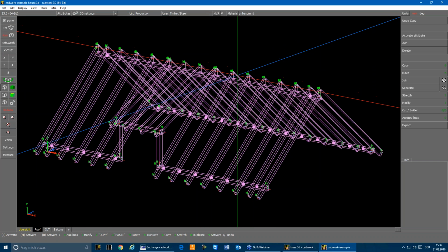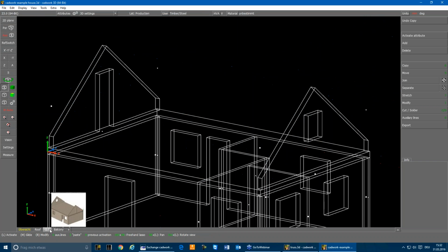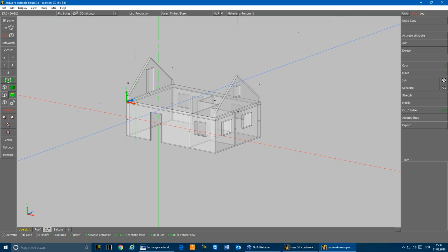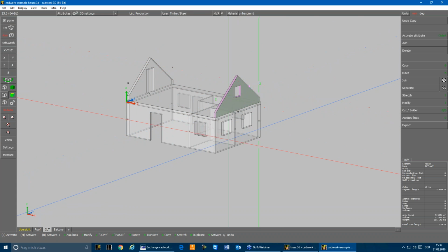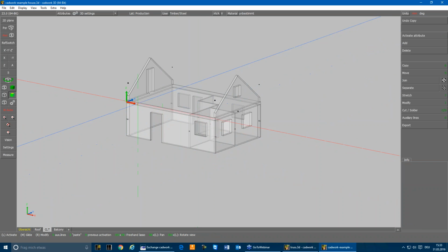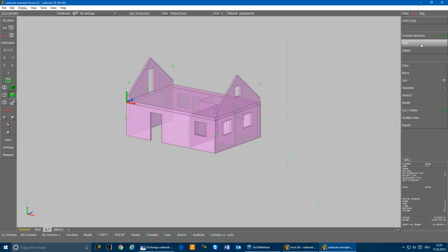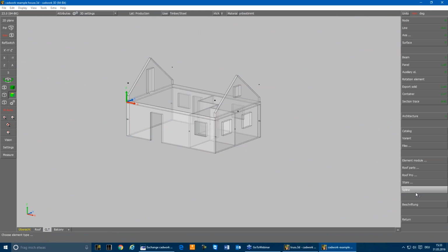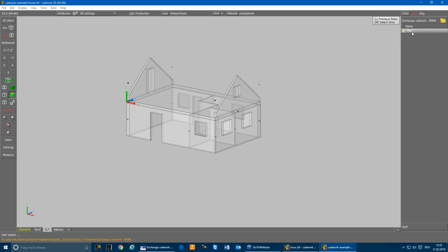So this was part 1. Part 2 will be the CLT parts, and the problem on CLT parts is that we can't work like a beam on this one. We need an additional element for the laminated walls and the floors, and this is a middle surface we should work with. And to define this, we just created a small variant tool again, which is in Add, Variants, current folder in this case. We call this one Middle Surface CLT.